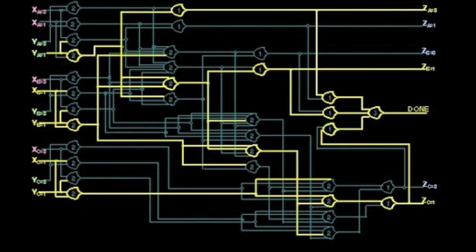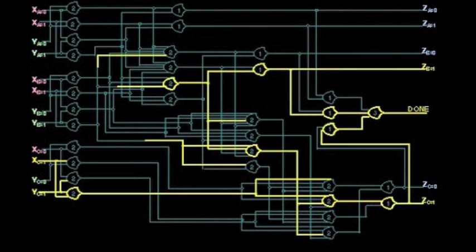So now the null wavefront begins propagating through, and with one exception, which we'll talk about in a minute, the null wavefront propagates with full logical determination, just like the data wavefront did. So if we look at our favorite gate here, one input transitioned to null, but the gate retains its output value at data. Only when the null propagates to the other input and the gate has complete null does it transition its output to null.